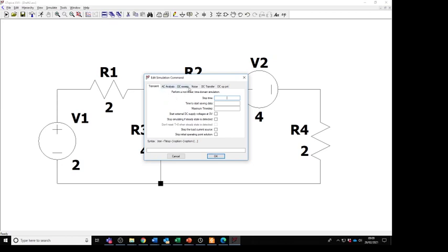So we'll look at these other ones in a bit, but the one we're interested in is this thing called a DC operating point. And helpfully it tells us: compute the DC operating point, treating capacitances as open circuits and inductances as short circuits. So this is DC analysis. This is what happens under static conditions, which is sort of what we want for biased conditions and what we want to solve these simple equations here.